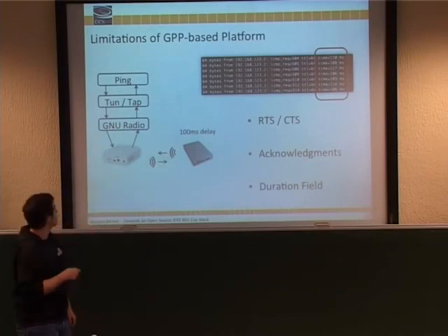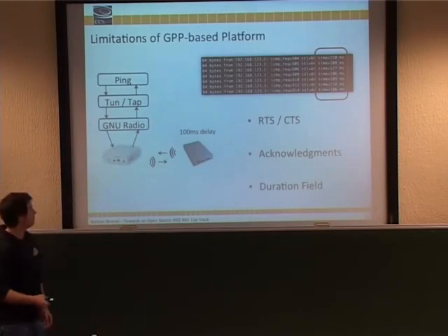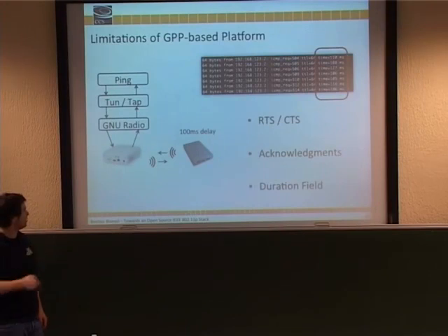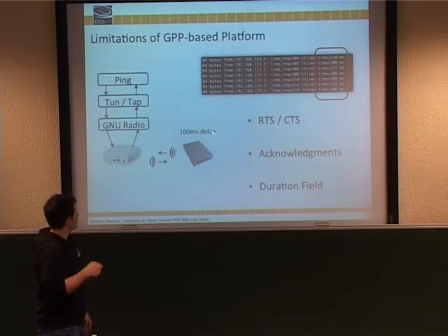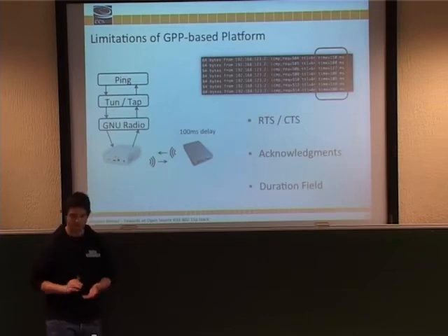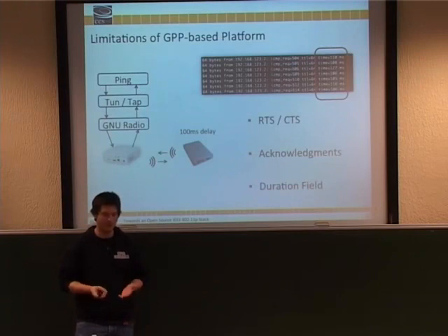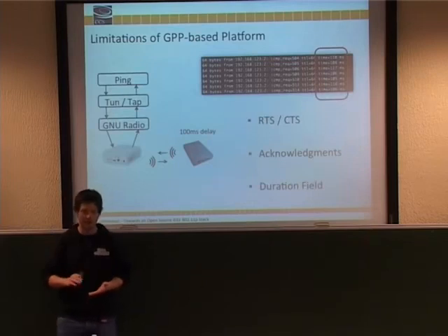And as I said, you can connect this thing to the Linux TCP/IP stack, for example. Then the easiest thing to do is to just ping the other device. You just use the ping command and send some frames back and forth between the USRP and some normal Wi-Fi card. And here we added 100 milliseconds delay artificially, but I know it's not a very exact way to measure delay. The point I want to make here is about the orders of magnitude. With this system, we are in the low millisecond scale for the delay.